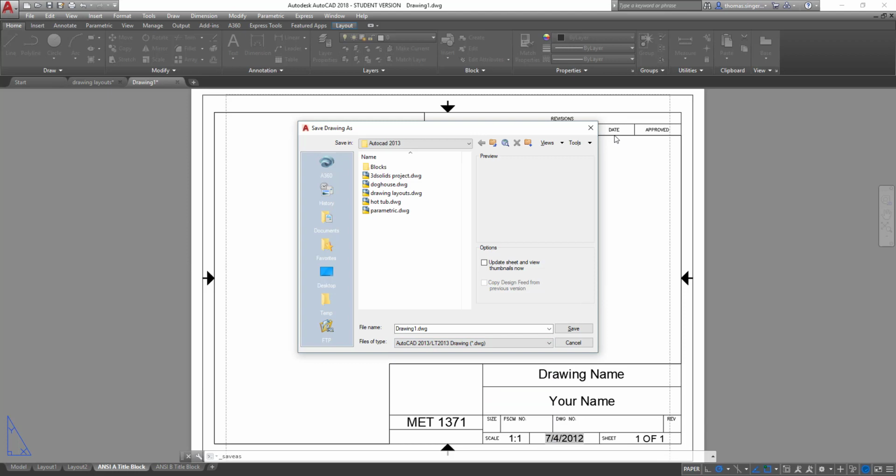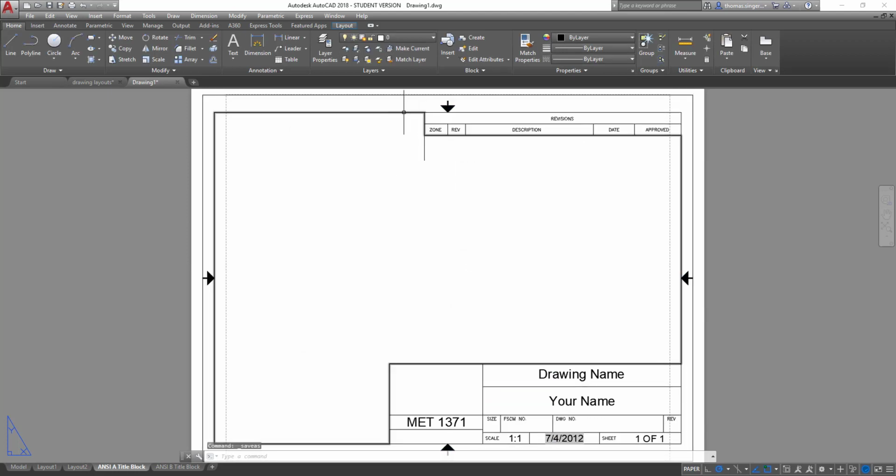So when I brought in this title block, you'll also notice that I have a layout, a viewport. This viewport is no different than what we were just working in the other drawing environment, except this happens to be a viewport that has a non-rectangular shape. So it's a unique shape. But the properties are exactly the same about this particular object. I may shoot another video on how to actually create one of these templates, but it's really simple. Like I said, just draw on a blank layout, just draw your title block or import it. This one actually happens to be a block.